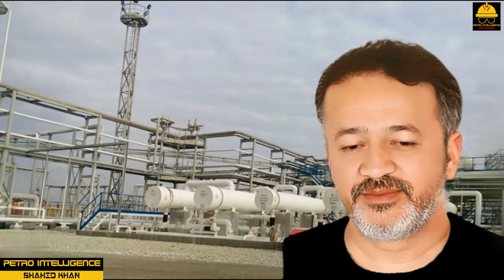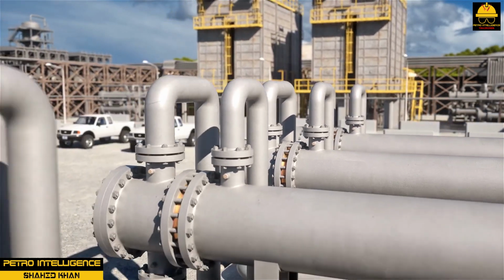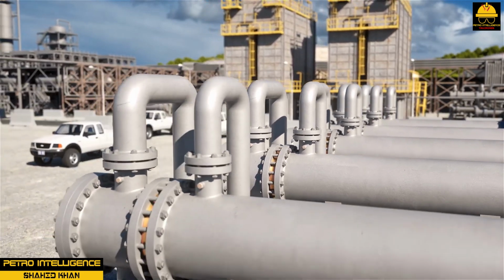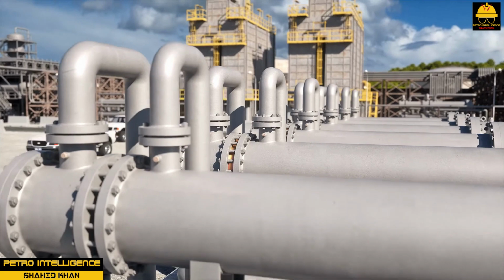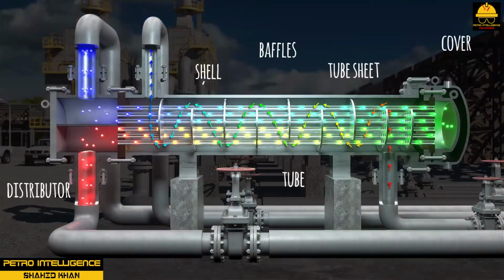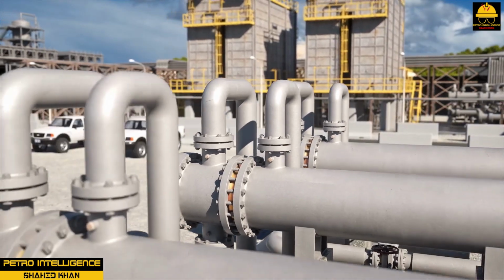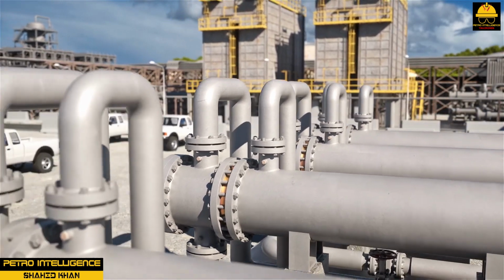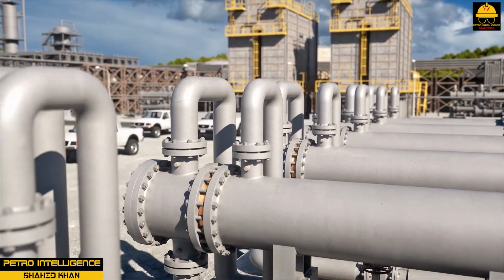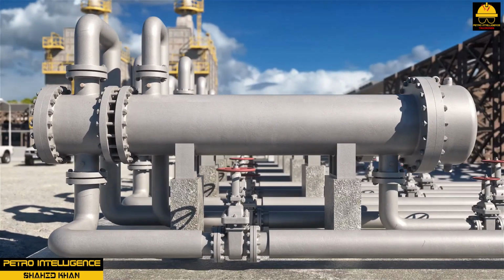Designs and components. Exchanger nomenclature uses the terms front end, shell or middle section, and rear end to refer to the three parts of shell and tube heat exchangers. The front end design of a heat exchanger varies depending on the type of service in which it will be used. The shell has 7 popular designs that are linked to the way flow moves through the shell. The rear end section of a heat exchanger is linked to the front end design. Industrial manufacturers are currently using over 9 popular designs.